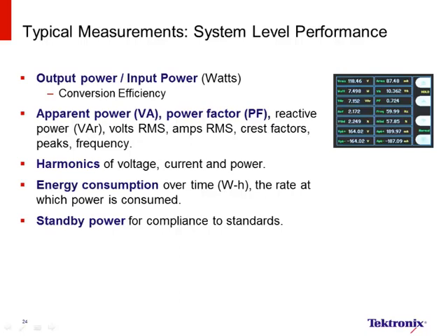Electrical energy consumption over a period of time is measured in watt hours. This is a requirement of Energy Star for many domestic products. And compliance to standby power regulations, which is becoming increasingly important and difficult, is another measurement performed by a power analyzer. We're going to focus on that shortly.